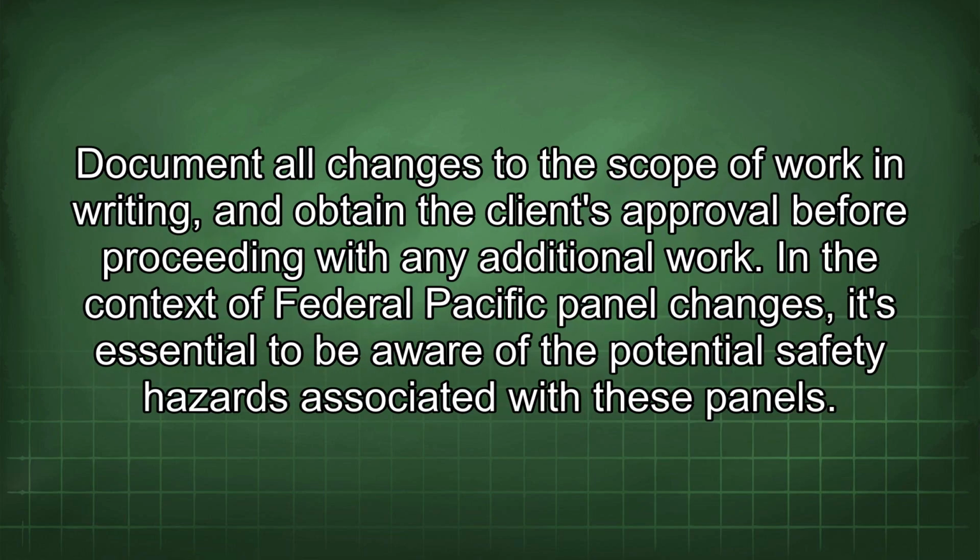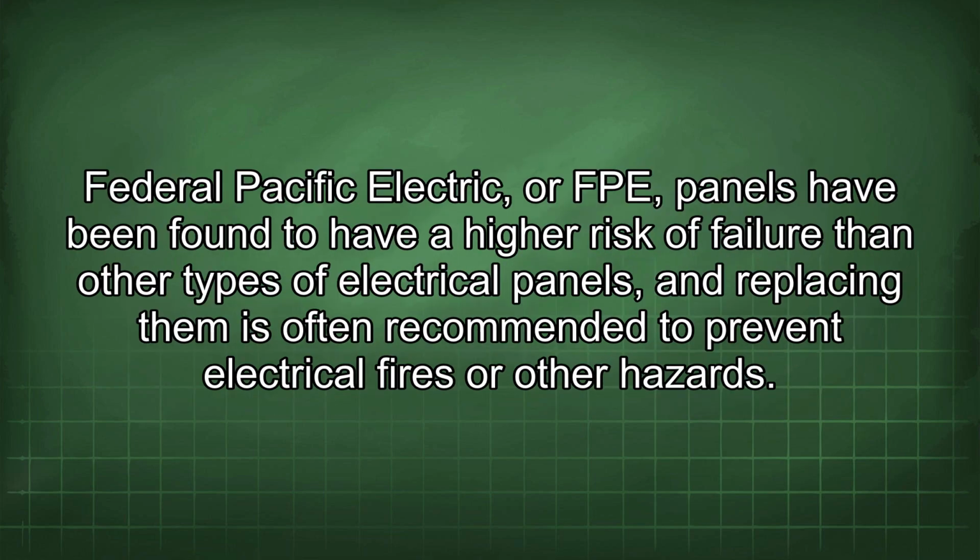Document all changes to the scope of work in writing and obtain the client's approval before proceeding with any additional work. In the context of Federal Pacific panel changes, it's essential to be aware of the potential safety hazards associated with these panels. Federal Pacific Electric, or FPE, panels have been found to have a higher risk of failure than other types of electrical panels, and replacing them is often recommended to prevent electrical fires or other hazards.